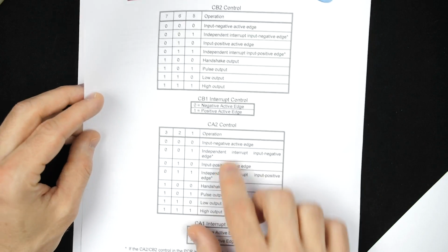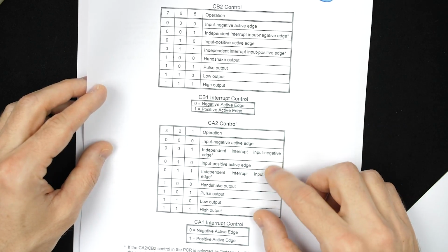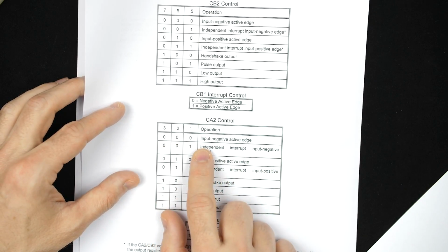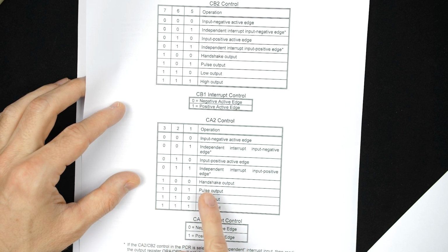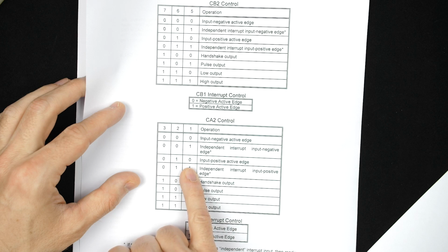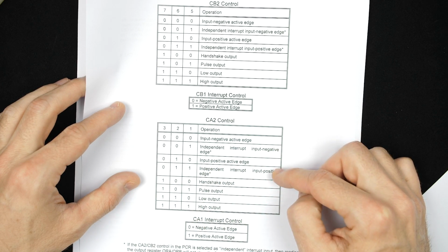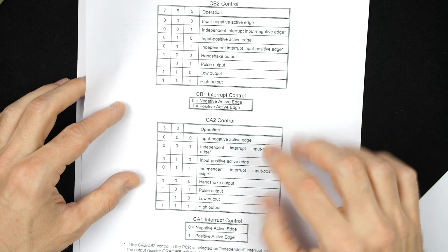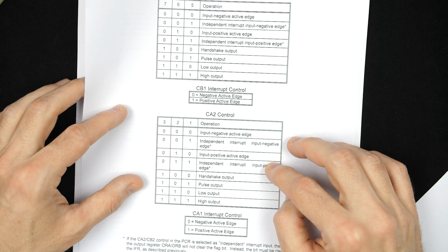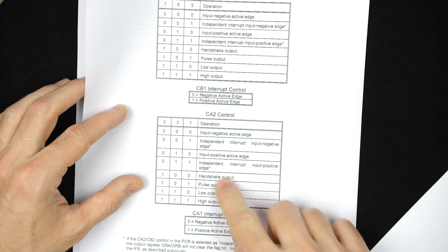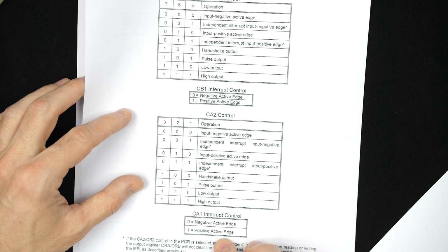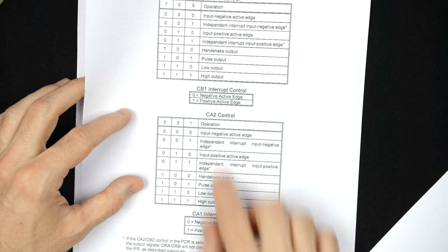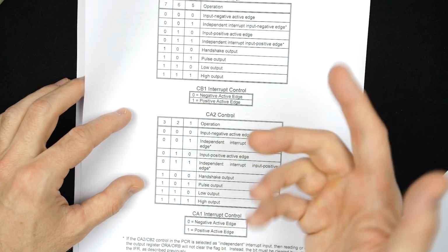You can do the same thing. So you can see both of these have a little bit more options to them because you've got 3 bits. But you can kind of do the same thing, because there's a negative active edge if you set them all to 0. There's a positive active edge if you set 0, 1, 0. There's also this sort of independent version, which you can read the note. It works very similarly, but the way you clear the interrupt is a little bit different. You can also use it if you're using this handshake option, which is described in the data sheet in a little more detail. Or you can also use those extra pins as just output pins. So you could set the pin to low, or you could set the pin to high, and it would just work as an output pin. So you get a little bit more flexibility with 2 of those pins.